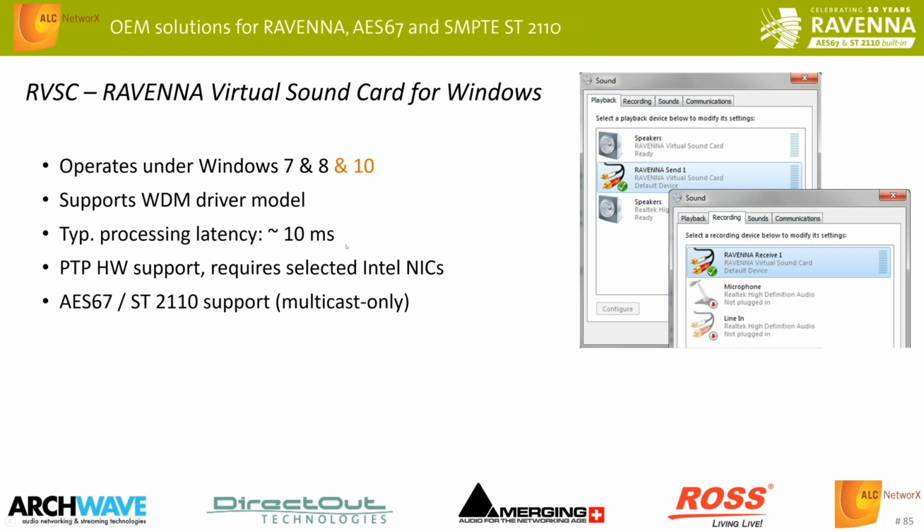That is because we have not written too much of the code in the kernel space, but only use the PTP interface and the audio driver in the kernel space, and all the other processing takes place in the user land or user space. So 10 milliseconds is what you can expect as a typical latency with the virtual sound card.